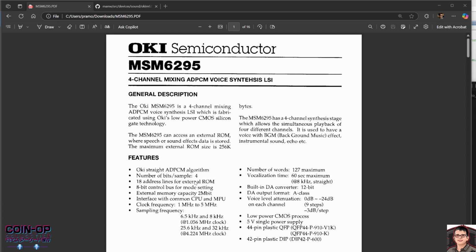Typically, what we do from an FPGA perspective is we put the master clock into something, and then we gate that master clock with a clock enable. What that means is, let's say your master clock is running at 96 or 48 or 128 megahertz, something high, something fast.